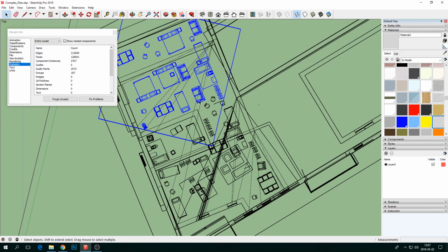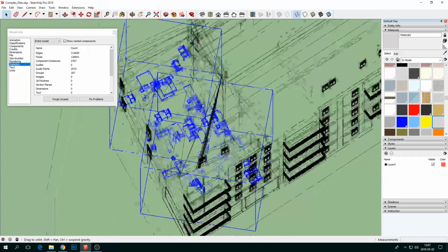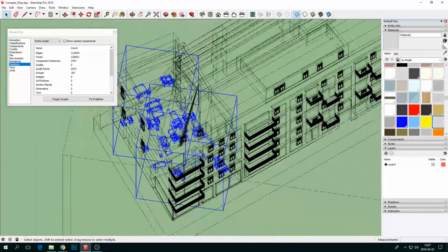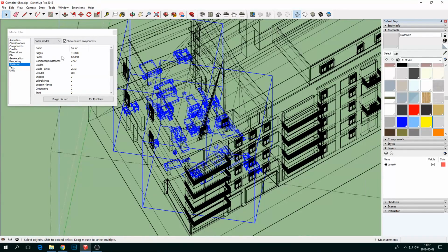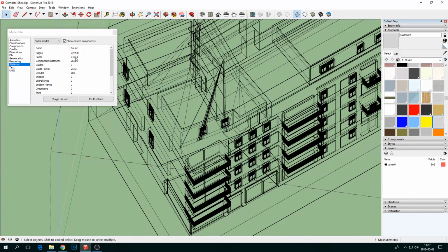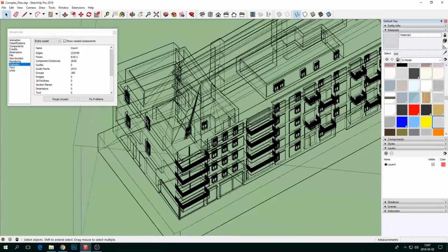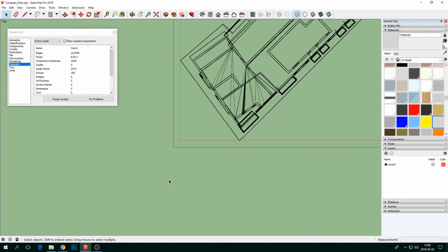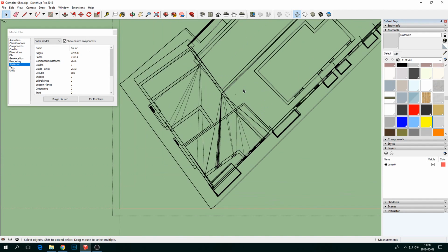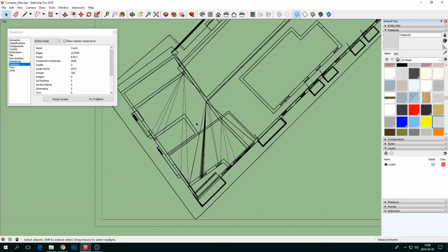So by clicking on those furnitures, we can select those, and they are grouped already, which is good. If you look now at the number of faces here when I'm deleting those objects, it goes down to about 50,000. That drops the faces. So this is good. Try to stand in the top view, look in the model, what it's containing inside, if there are any unnecessary furnitures or whatsoever that you can erase.